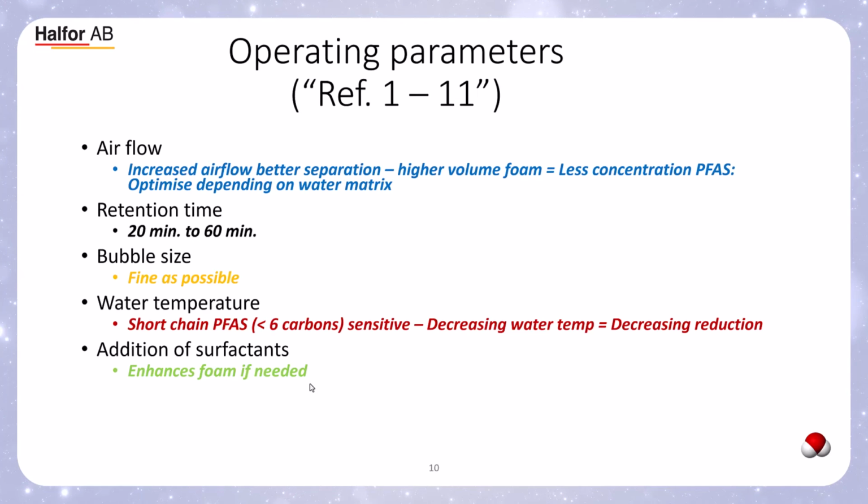Surfactants or addition of surfactants, all depending on your matrix. Probably if you're looking at removing PFAS or PFOA, you don't need to use surfactants, maybe depending on the water matrix. But if you're looking at the shorter chain PFASs, probably you need to look at a surfactant that will help you remove the PFASs from your water.